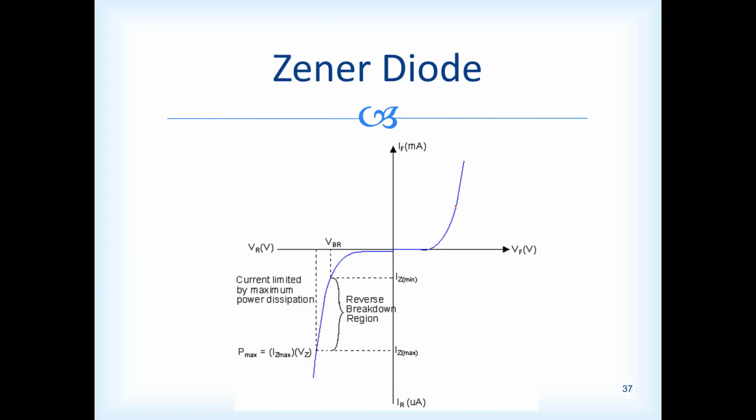Right, this is what this is. If you notice, this looks like a normal diode characteristic curve. In forward bias, it goes curvy like that, exponentially upwards, with a value of 0.7 V. Under reverse bias, there is a condition where the VBR, the breakdown, occurs.